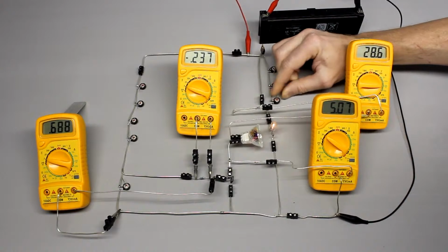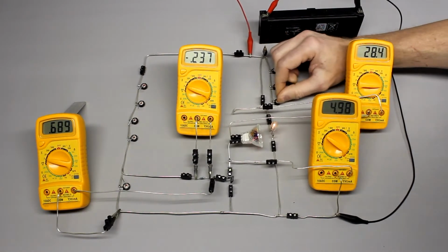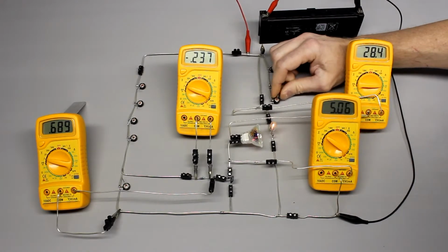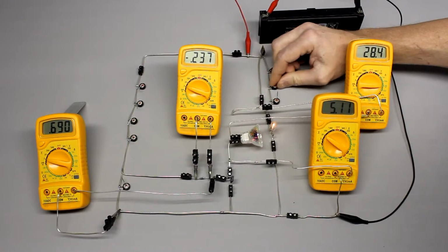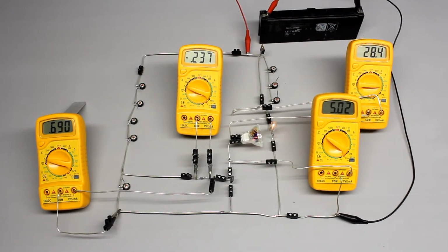After adjusting a certain voltage drop at the base pin, the voltage drop at the collector pin has to be readjusted to 5 volts. As you can see, this voltage is increasing slowly, making it hard to adjust a constant voltage with the help of the PNP transistor.